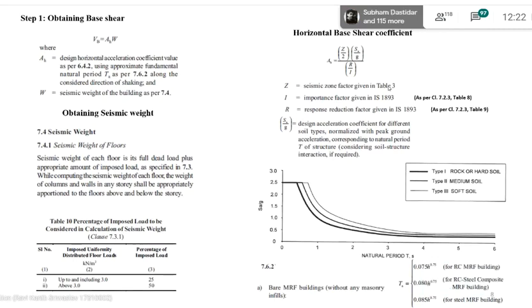But see, let's consider some level of earthquake is coming, and if you are not designing for that level, if you are designing for a lower level of earthquake, what will happen is your building may go into non-linear ranges, right?